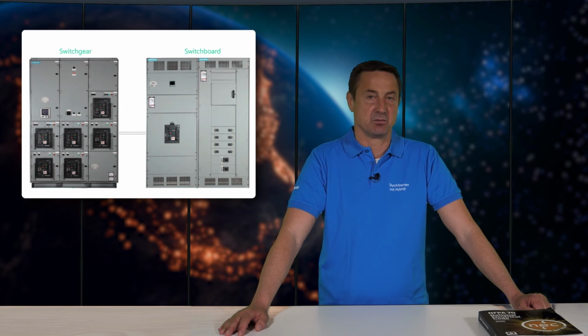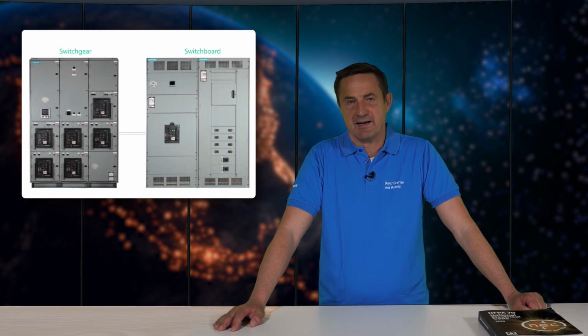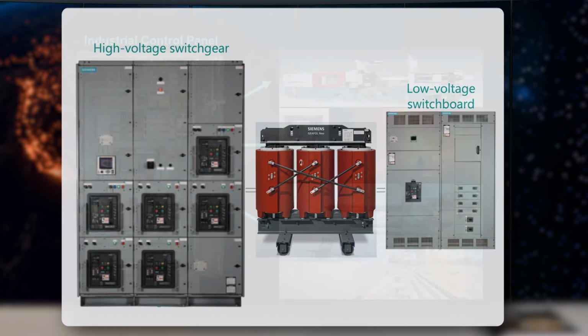They may have more than one primary input service section, which contains switching devices to manage different and independent energy sources. In the case of a failure of one energy supply, the switchgear will switch over to a redundancy source automatically, and the energy supply for sensitive buildings like hospitals will be guaranteed without any interruption. Normally, switchgear supplies the energy to one or more switchboards. High voltage switchgears, which distribute more than 1000 volts, must feed a huge power transformer for generating the appropriate voltage before they can supply the energy for the low voltage switchboards.